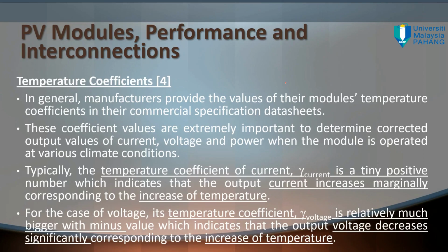If not, you think it's 100 watt, it's actually not. For example, the IMP written in the description is 6.0, but when you try to look for the data sheet, you cannot find it. And then when you bought it and tried your system, only 4 amps. Why? That's the problem. It becomes apparent after you get the module in your hand.